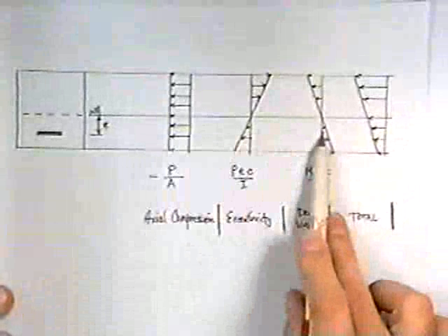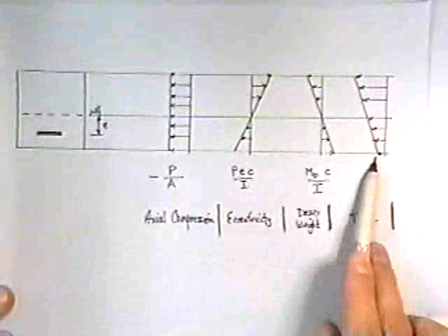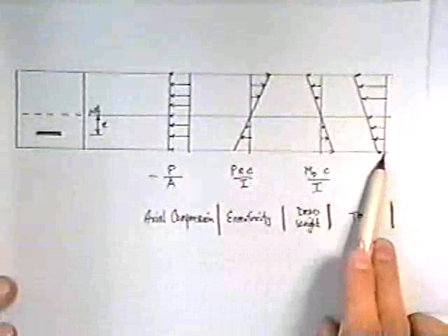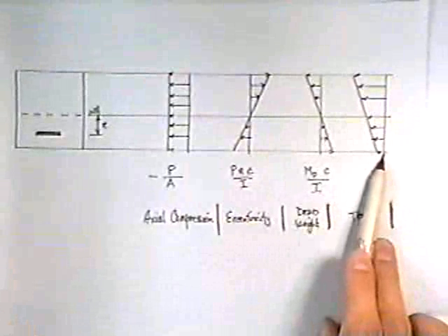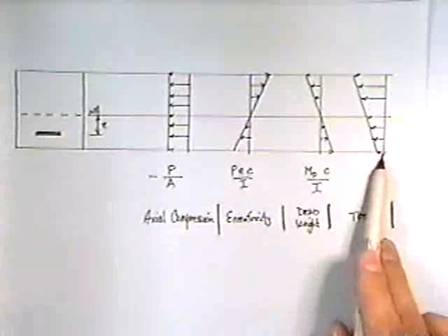When you add the 1, 2, 3 cases together, and you make sure that neither the bottom part nor the top part goes into tension, do you need any additional steel? No, because the concrete doesn't crack. That's the whole idea behind pre-stressed concrete, that you can keep a concrete section from cracking its full length. That's why you can go to big spans on bridges and things, because when the concrete doesn't crack, it has a bigger stiffness, it can take more load with less deflection.